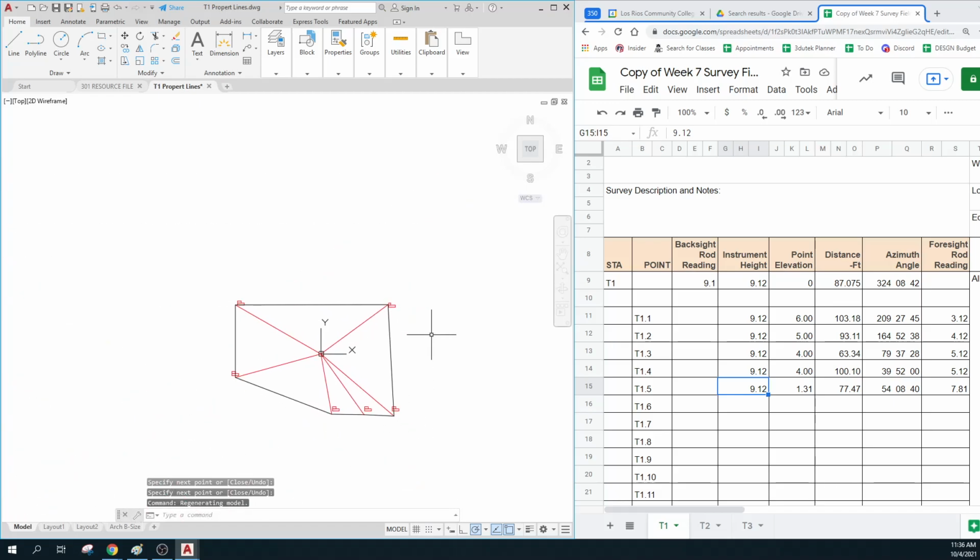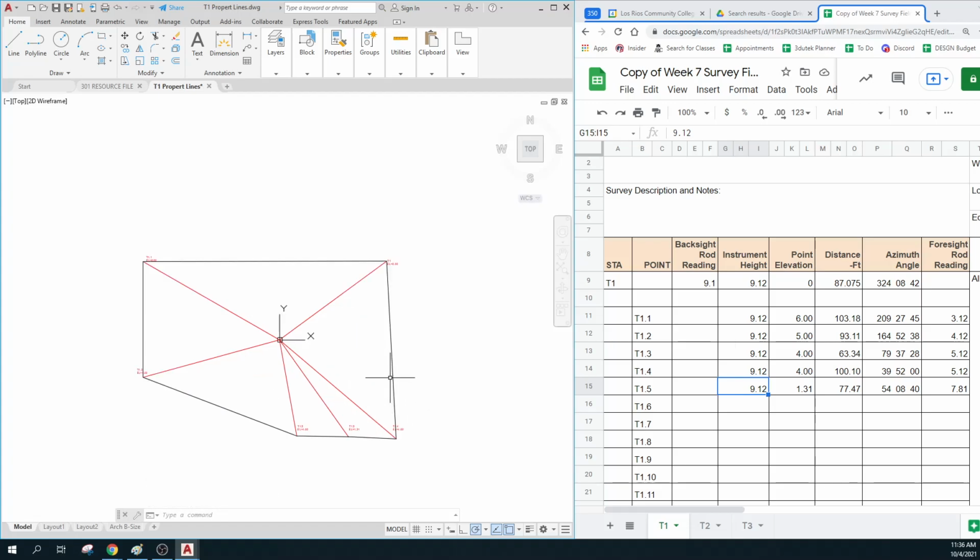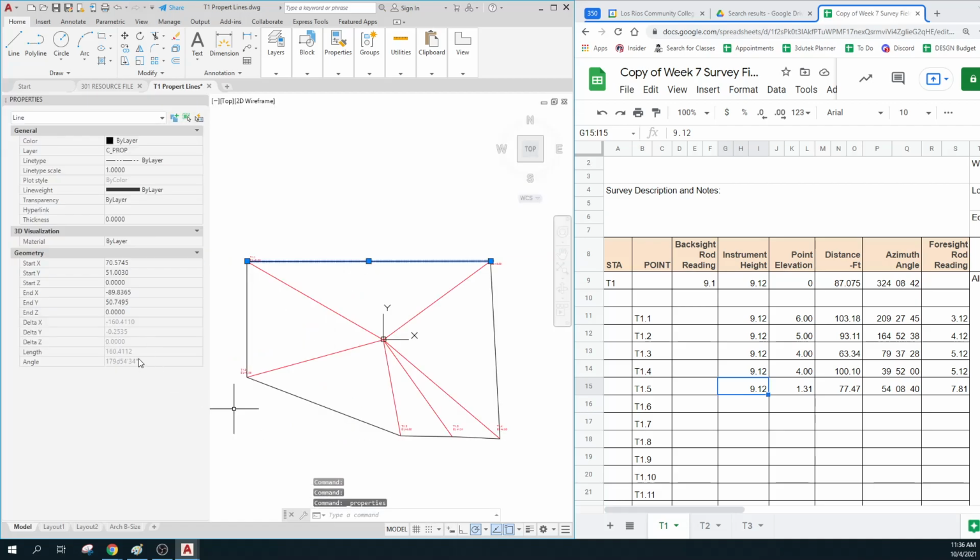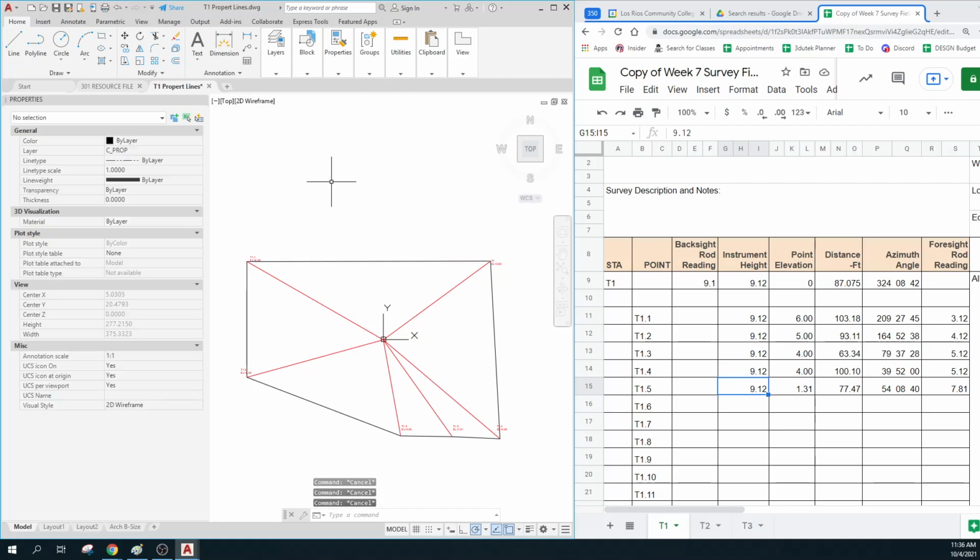And that should look somewhat familiar. It's not exactly the same, but what is that one? Should be very close to your DT100. Look at that. That was supposed to be 160 due west, and you're pretty close. 179.5436.